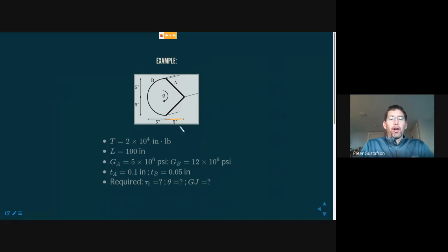The overall dimensions here are going to be 5. The semicircle is going to have a radius of 5, and the triangular section is going to have a horizontal length of 5. Obviously, it's got a vertical length of 10, which is twice the radius of the semicircle. Now, Scott, this doesn't necessarily follow that rule of thumb that I gave you. This is more for simple calculation than for realistic scenarios. I've not done a buckling analysis to determine if this structure would buckle, but that's certainly something you would do in a real-world scenario.